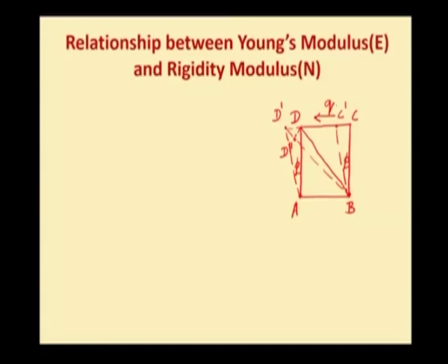Now, let us consider this small triangle D dash, D and D double dash. So, I am drawing it here. This point will be D dash, this point is D double dash and here we have D. The angle D D dash D double dash will be more or less 45 degree. Actually, it will be slightly less than 45 degree only by a very small amount, hence this angle can be taken as 45 degree. So, this angle D dash D double dash D will be more or less 90 degree. So, this triangle will be a right angle triangle. Now, if we take cos of 45 degree, we will get the adjacent side D dash D double dash divided by the hypotenuse D D dash. So, D dash D double dash will be equal to cos 45 into D D dash.